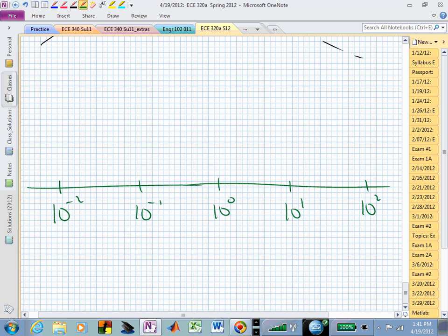Now, what do we have contributing? What did the constant contribute? 0, so we don't have to do anything. What did the 0 at the origin contribute? Plus 90 for all frequencies. That's the 0 at the origin contribution. What about the pole at 0.1?